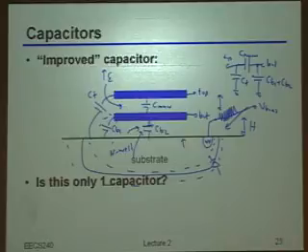That's actually true. Typically, the N wells are thick enough that you can't exactly do that, but it's a very similar idea. So you increase the depletion region, which is the capacitance. The capacitance gets smaller, you mean, but yes. Yeah, so you basically said exactly what I was going after. So if I apply a really big bias right there, indeed what will happen is I will increase the width of that depletion region. That will make the capacitance associated with that region get smaller, right?